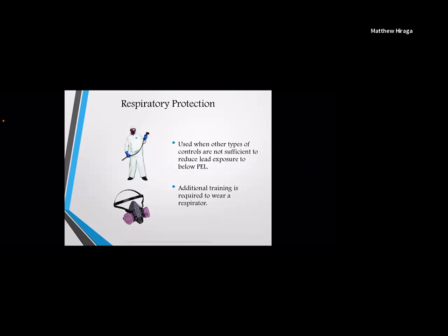Keep in mind, anytime you wear a respirator, you have to be clean shaven in the area that the mask is going to be touching your face. So anywhere the mask makes contact with your face, no facial hair. And then if you have facial hair that's not touching, it cannot interfere with the movement of the one-way valve. Your respirator is going to have at least 3 one-way valves, right? 2 on your filter inhale and then 1 on your exhale. The hair cannot affect the movement of that valve.